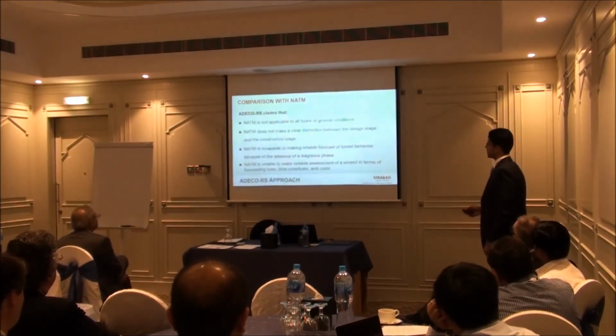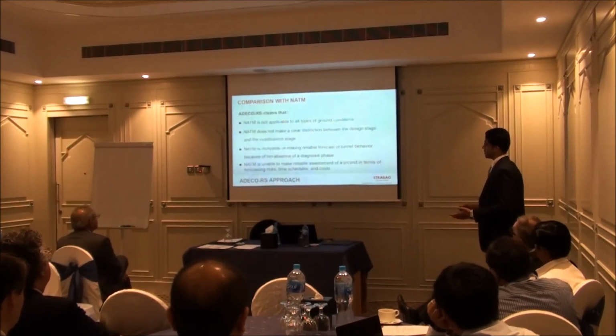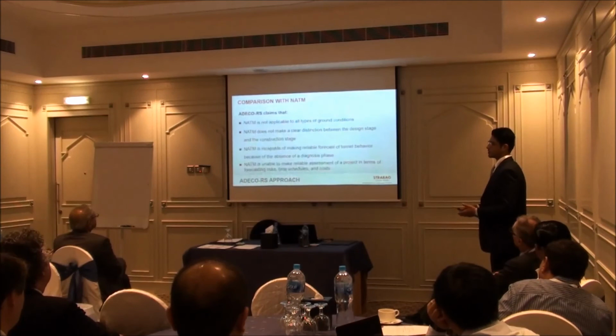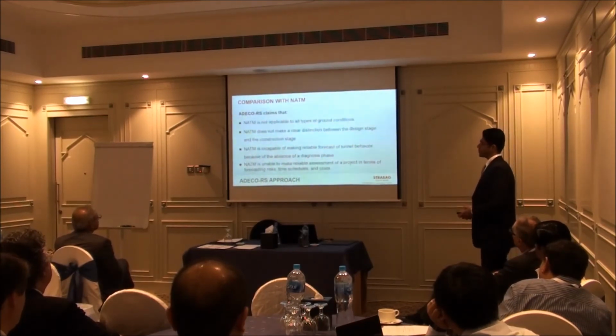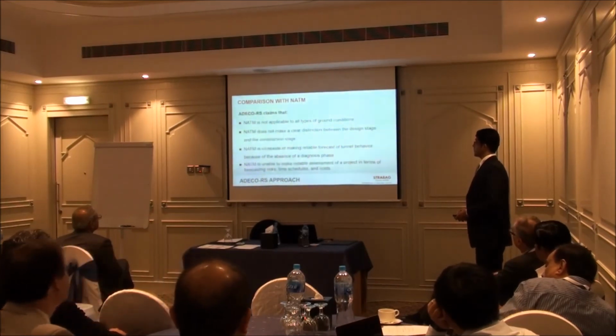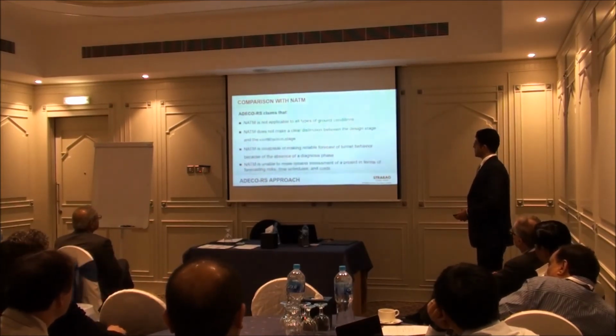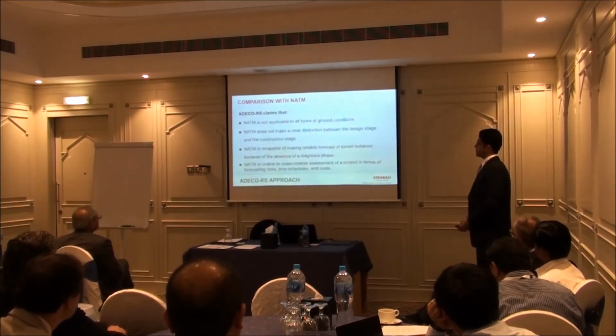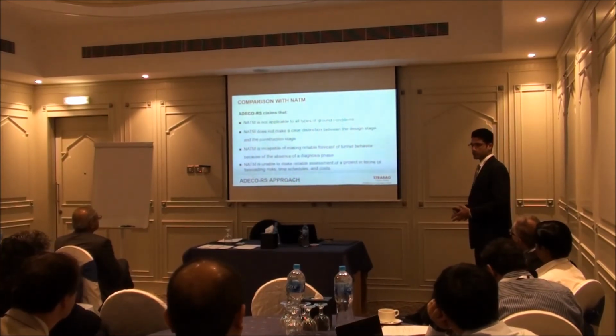Some final points which the ADECO RS method claims that the New Austrian Tunneling Method cannot do are listed here. They claim the New Austrian Tunneling Method cannot be used in all types of rock conditions, does not distinguish between construction and design stage very clearly, and is not able to make proper forecasting of costs, because it's a design as you go approach.